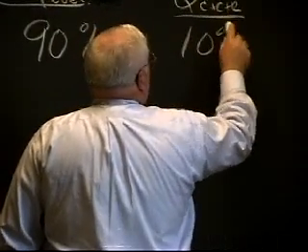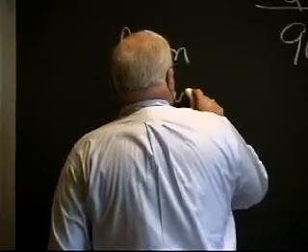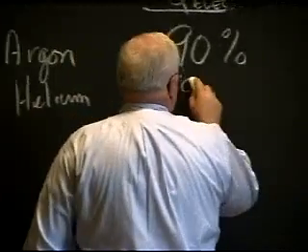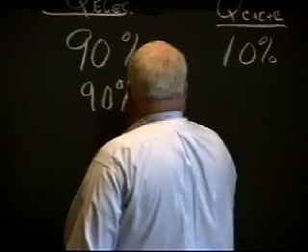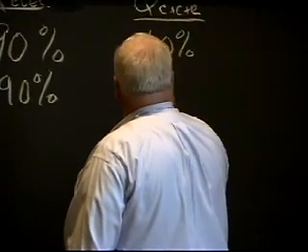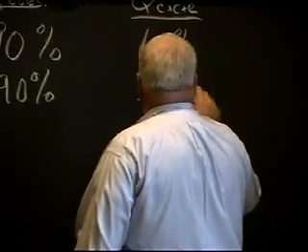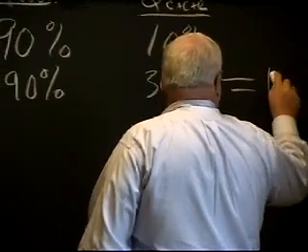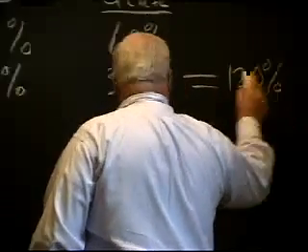With helium, because of its higher thermal conductivity, I'd get the same electron heating because it's the same current, but I might get 30% or something, a 3-fold increase in the convection part. And so I get 120%, or a 20% overall increase.